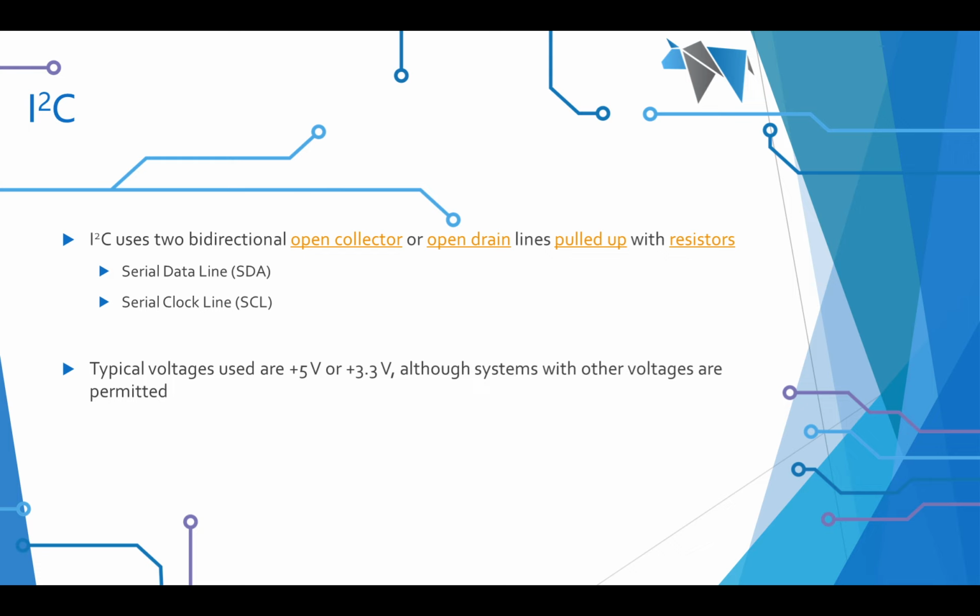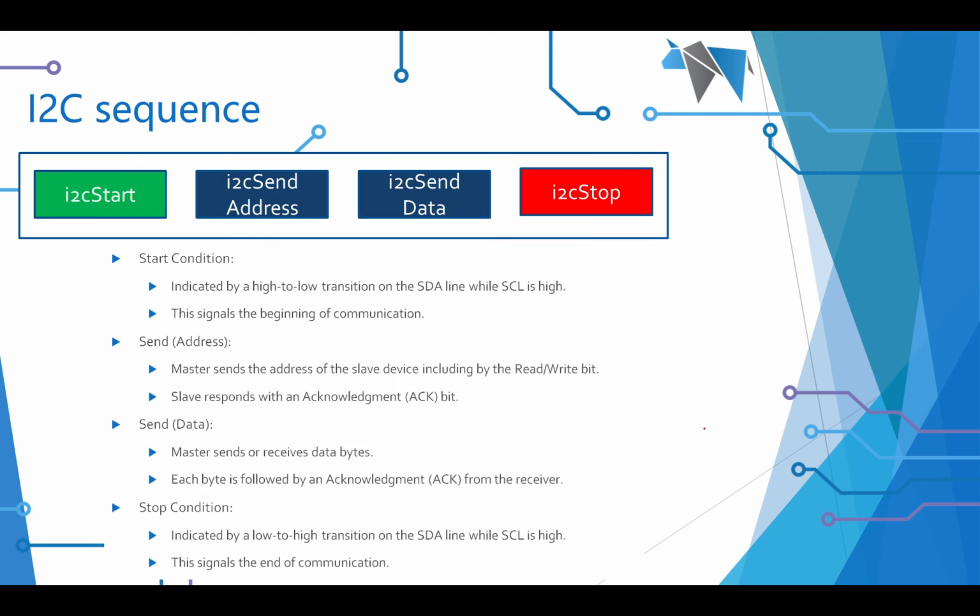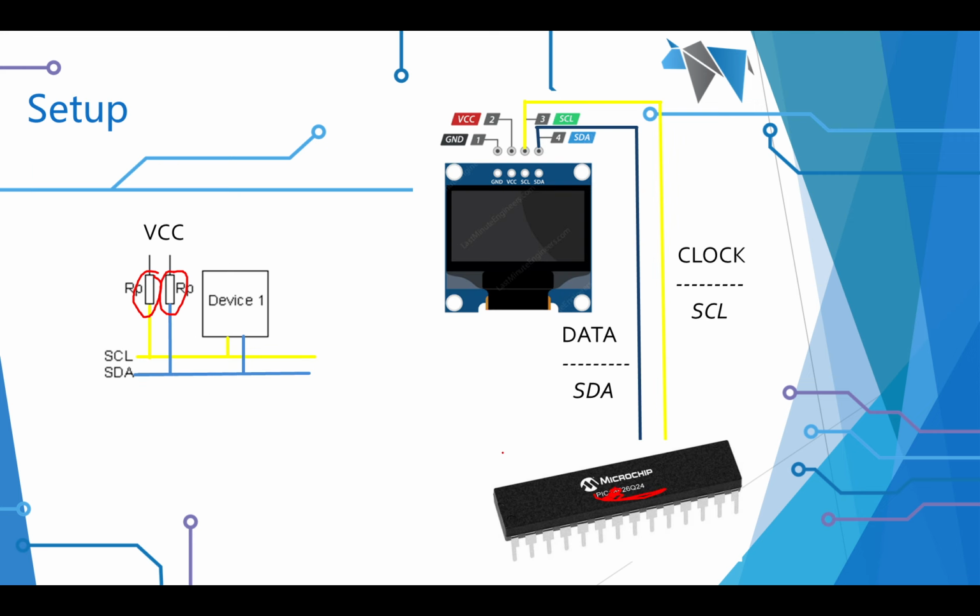I2C is, as I said in the previous video, open collector, and it has an open drain characteristic. That means the lines are pulled high with resistors. We'll look at those. The 2 lines we're pulling up are the serial data line and the serial clock line. Now, I'm running this at 5 volts. Some GLCDs run at 3, so make sure you know what voltage yours is. I've got my 2 pull-up resistors fitted. How do I know? Because it's responding to I2C discovery, and I've got it connected in as shown. Ignore the chip here, by the way. That's just an old picture, okay?